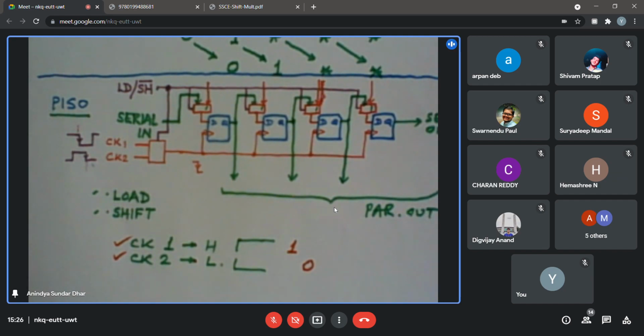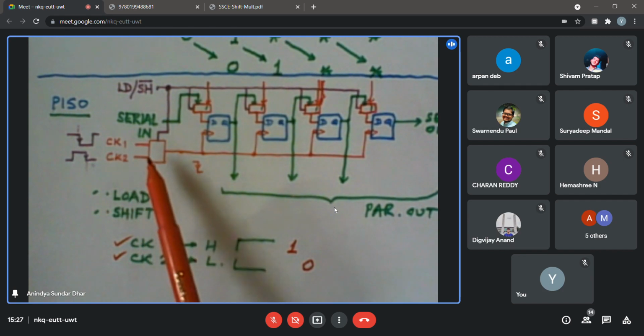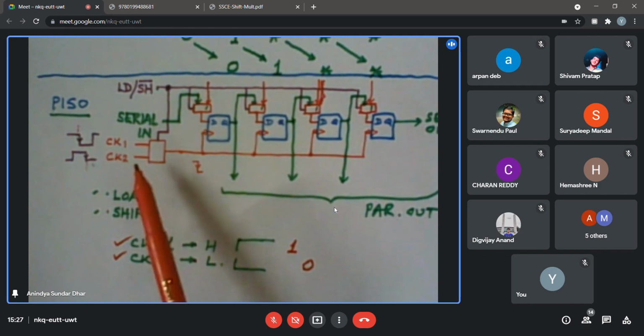I may not have to overburden you at this moment, but still, because there is a provision, I am telling you, it might happen in the lab when you are using 7495. But here we may tie them together to avoid any such confusion, because it is a small system. We use a single clock, not a double clock. But still, as a cautionary statement, I should mention that there could be a spurious edge. So the rule in general is that whenever you are changing, the two clocks should be high.